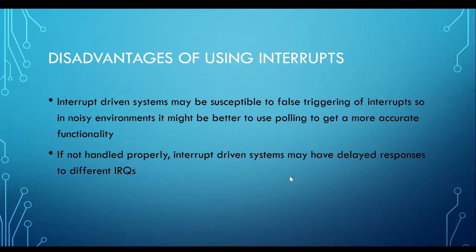Interrupt-driven system may be susceptible to false triggering. Okay, this is very true. When you have interrupt, of course you have problems. Every single engineering is a trade-off. When you have an interrupt, advantage is power consumption. Disadvantage is susceptible to false trigger.